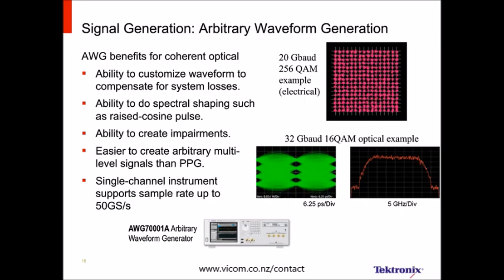So I think what we're seeing here in this ability to do the 256 QAM at 20 gigabaud is that because the products in question have a lot more bandwidth than that, once you apply that low pass filter, you actually get effectively a higher number of bits. So sometimes when you look at, for example, digitizers, having more samples per second than you really need can turn out to be a big advantage because then you can use low pass filtering to really improve your signal to noise ratio.